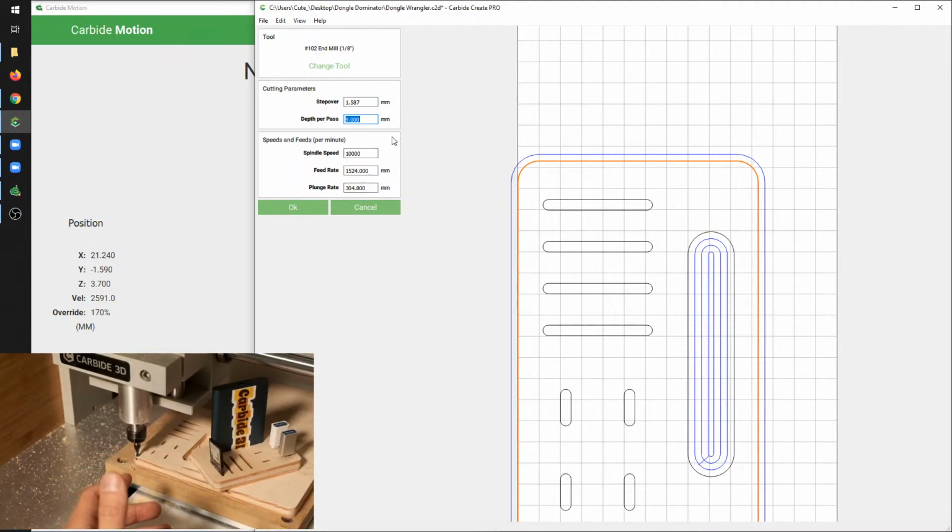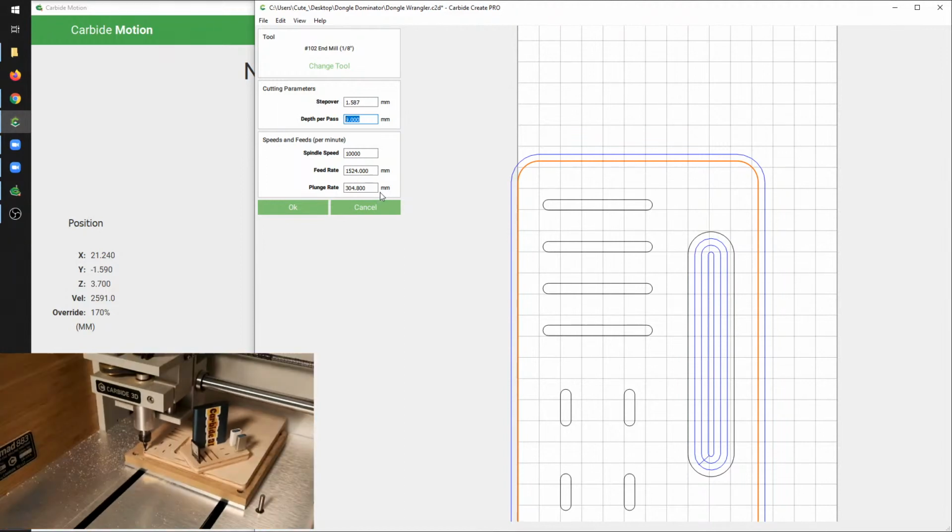I saved that. I probably shouldn't have. And so when I exported this last toolpath, it thought it should plunge all the way through the stock and then try and route out the entire piece. Now the work holding would have given, the tool probably would have given, the spindle definitely couldn't handle it. But this gives you an idea of what happens when you crash a pretty friendly desktop machine. It's not the end of the world, nothing terrible happens.